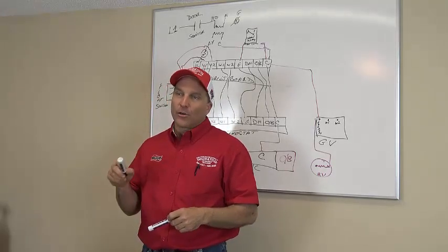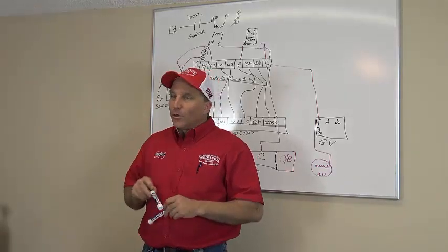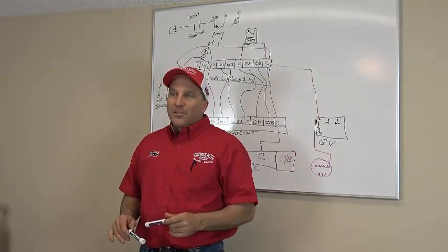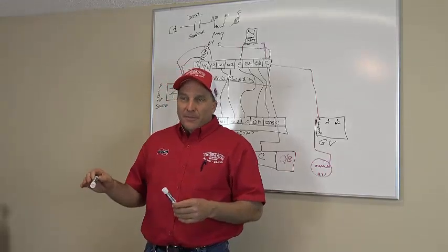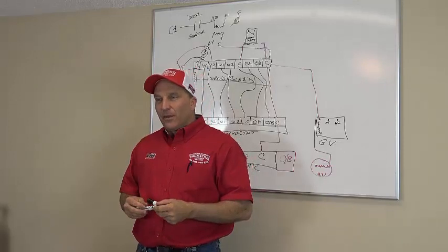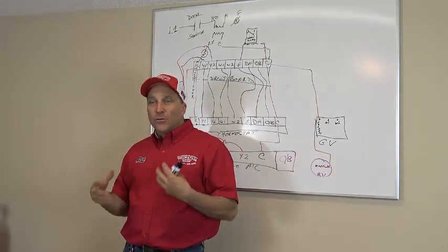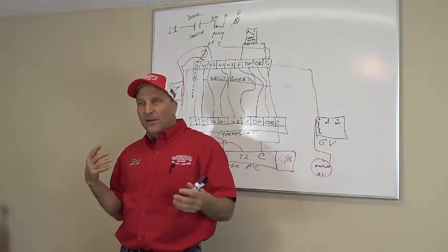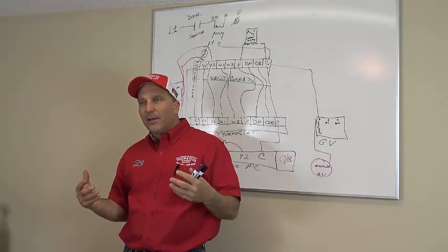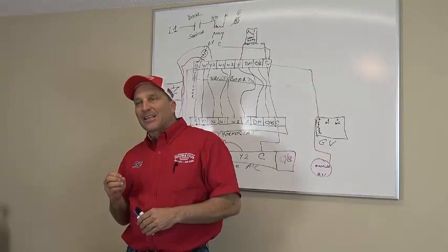That's very hard to go find, too. It's not because you know what you're looking for. You just got to go find it. So anytime you're reading less voltage like that, 70 volts, 72 volts is what I normally find, sometimes 54 volts, and you're looking for 110 volts, and you're finding 70 or 50 or something like that, you have a bad common somewhere, okay? Or you have a bad connection somewhere.